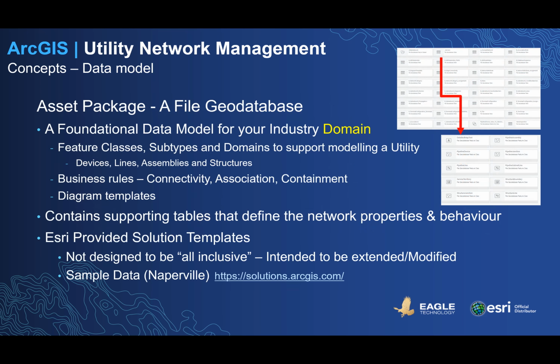To understand some of the key data concepts, we'll first take a look at asset packages. An asset package is a particular flavor of file geodatabase which is designed for each of your industry's domain network requirements. The asset package is where you will define your features, subtypes, domains, and other operational and business attribution that you might have. It's also a collection of other metatables contained in an asset package that define how your network will behave. Business rules for connectivity, attachment, containment, and schematic diagram templates you can use to build out your own